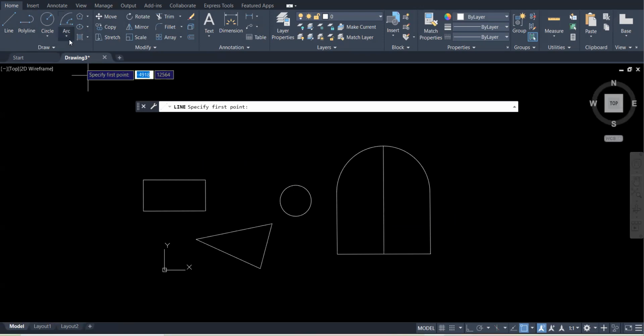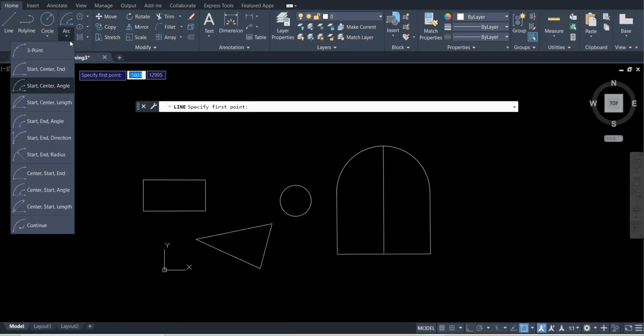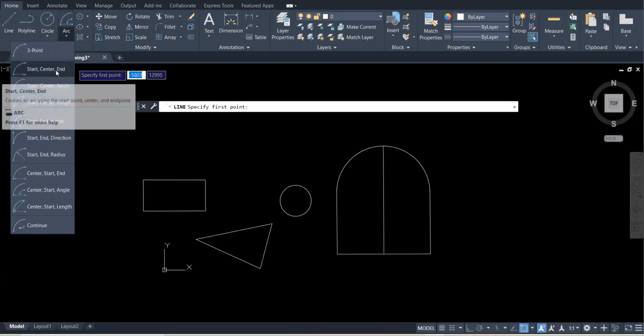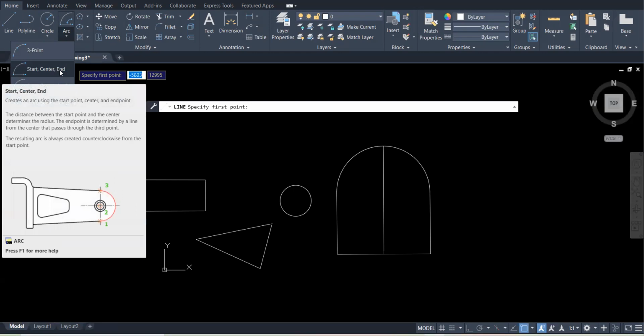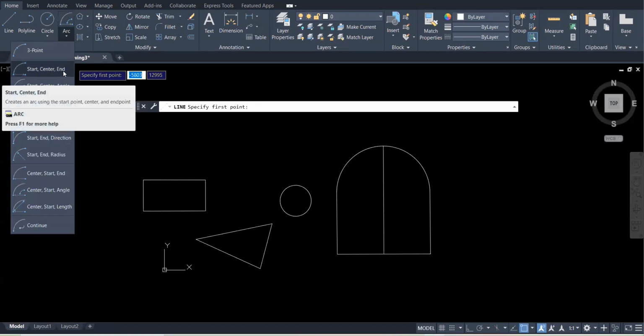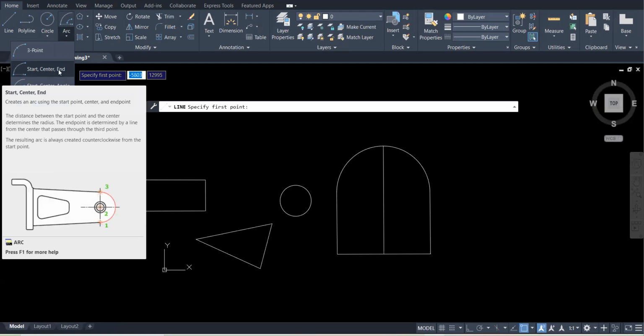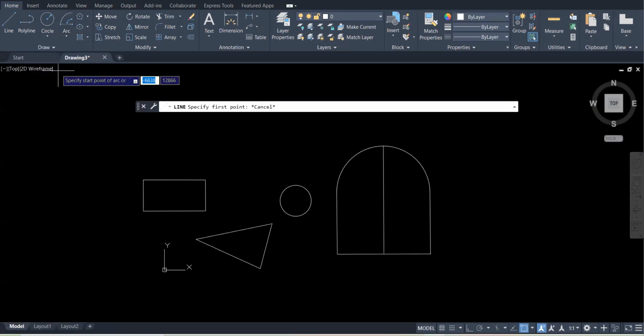All right. Now let's start doing the arc command. Since we turned this on, the most important thing, as we said, is that we have those two points, the endpoint and the midpoint, turned on, because we're going to be using them a lot with the arc command. With the arc command, we need three points to be able to decide; that's how arcs are created. They are created using three points, and we need to make sure that those three points are identified before we start creating the arc.